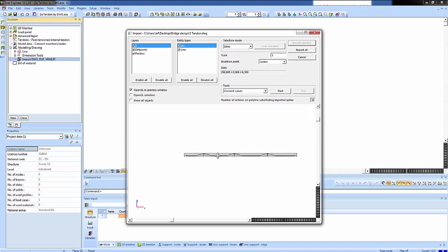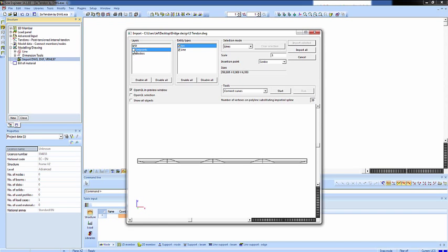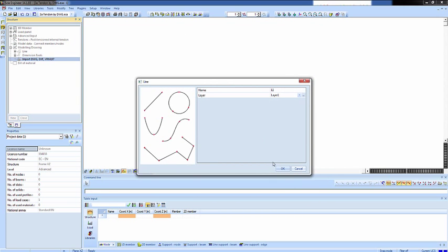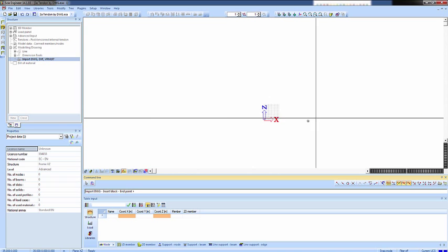Now I can also use the different layers that are in the file. So I'm going to deactivate the lines, arcs, def point. Actually, I just want the prestress part. Okay, that's perfect. I can use this. Now these lines are separated parts. I'm going to combine them. I have the tool for this. Start, select them, run, and I'm going to import them. Let's say I'm going to take this one and import selected. Choose OK, and I can place it here somewhere in the project.